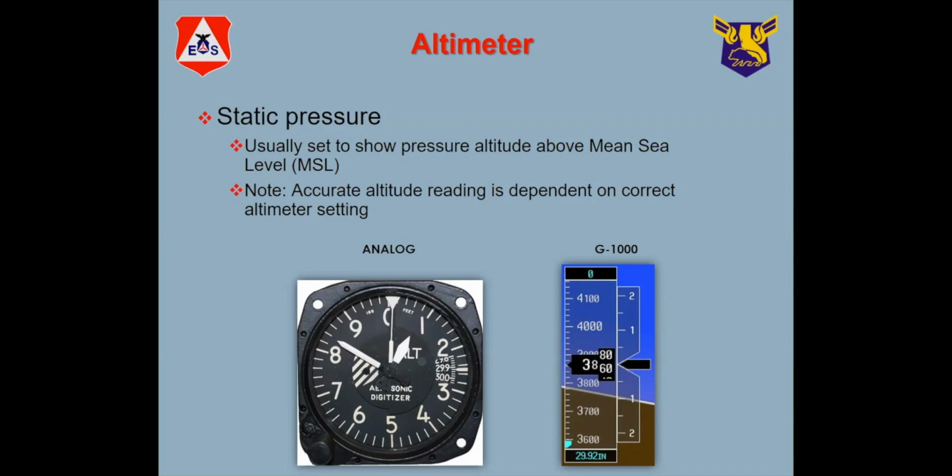So all an altimeter is, is a pressure gauge, but instead of being calibrated in PSI like a tire pressure gauge, it's calibrated in feet. And it assumes a standard atmosphere. But if the atmosphere isn't standard, if it's higher pressure than normal, a high pressure area, then that air is going to be denser than normal. And so that altimeter would read lower than actual altitude.